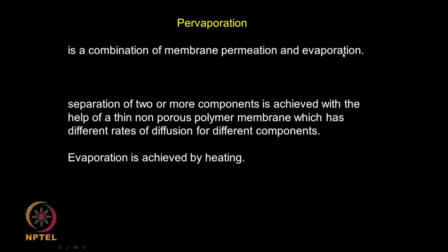So, the solution is initially evaporated by applying some heat as well as a high vacuum, and then the solute molecules permeate or diffuse through the membrane material because there is an affinity of the solute for the membrane material. So, it diffuses and goes to the other side where it becomes a liquid again, and that way it is collected.